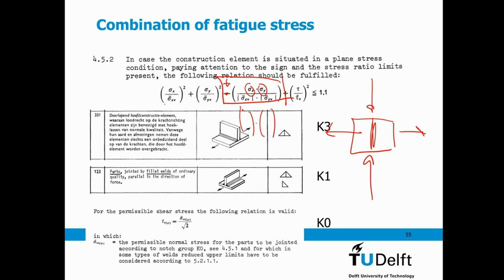So although this is a logical consequence, this can have odd effects if I have stress variations which are very close, with a kappa value close to -1. What does that mean? That means that my maximum stress and my minimum stress are close by.